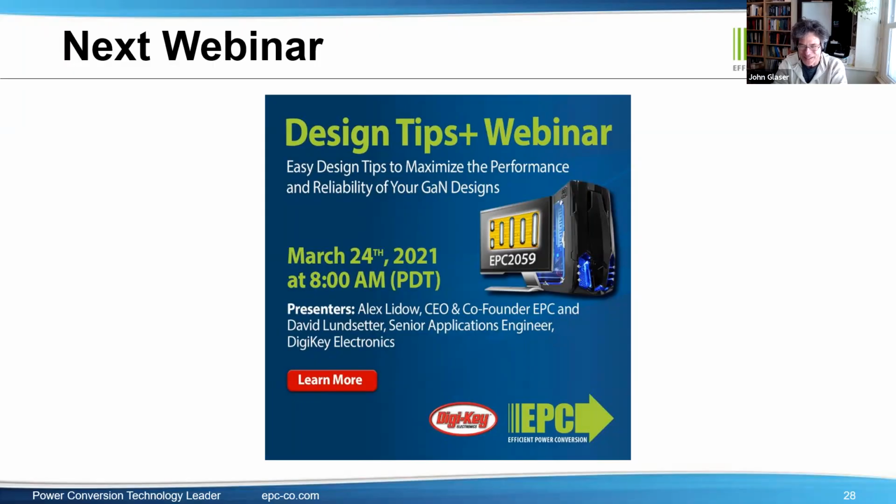And as an aside, and this has nothing to do with GaN actually, attack your EMI problems up front, right? If you keep your inductances low and think about it up front, you'll save a lot of trouble in the end. It's hard to put band-aids on at the end. I'd also like to add that with very fast rise and fall times, your frequency spectrum tends to be out in the very high frequency range, which is somewhat easier to filter out as well. And a lot of these lidar systems are in metal cans, so the problems have been solved, and it's just solid, straightforward engineering to do it.